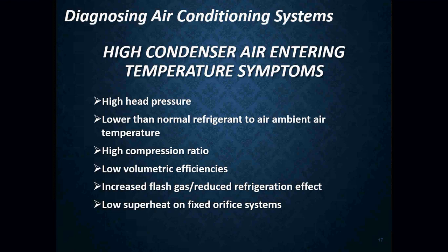The condenser cannot reject as much heat as this lowers your temperature difference and will accumulate the heat. The accumulated heat forces the condensing temperature to elevate to a temperature difference where the heat can be rejected. The temperature difference is the driving potential for our heat transfer, which is what we are actually trying to achieve.